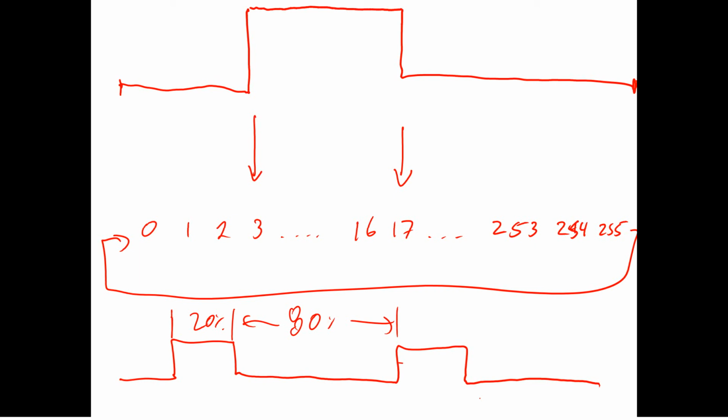And this is what gives us our pulse width modulation. Normally, you just go high at 0 and set some value where you go low. Whatever value you set to go low at is directly related to the duty cycle of the output.